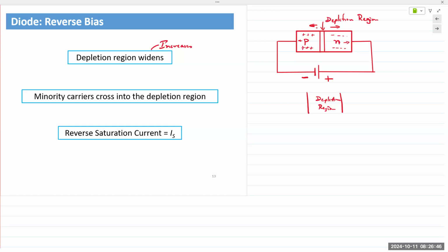So the ideal diode model, basically we take the X and Y axis and say positive X, diode is on; negative X, diode is off. So that's the ideal diode model. We simply have two states, on and off. Then there is an extension of the ideal diode model where we say the diode is on, but it requires about 0.6 or 0.7 volts to turn on, and so we put a battery or a voltage source in front of the diode. Again, there are various different models.